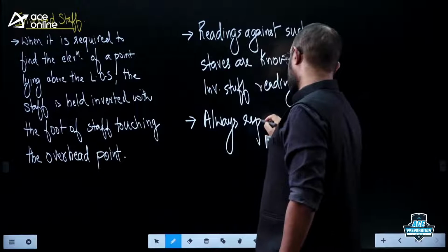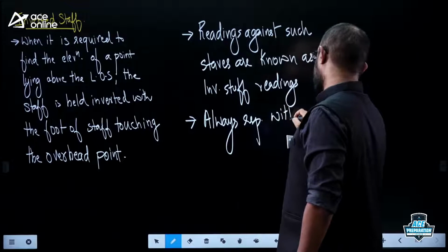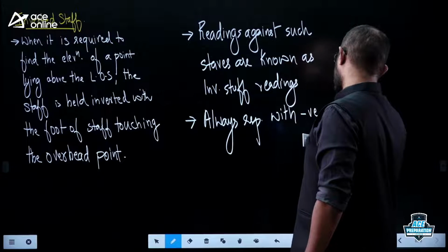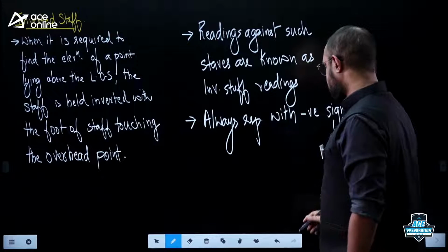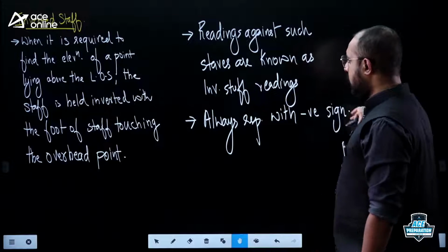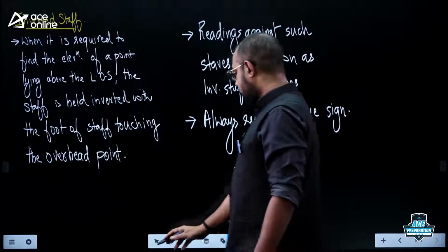Inverted staff readings are always represented with the negative sign. So remember that. This is what we call our inverted staff reading.